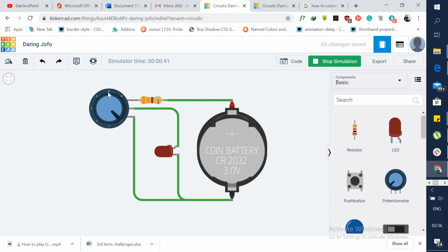If you Google and search for the potentiometer, you see that the wiper is like a strip, a resistance strip. So currently the current is facing a large resistance. As you increase, you are reducing the length of the resistor, hence decreasing the resistance, hence the current becomes more, hence the brightness begins to show, and more and more. So you have it very bright.